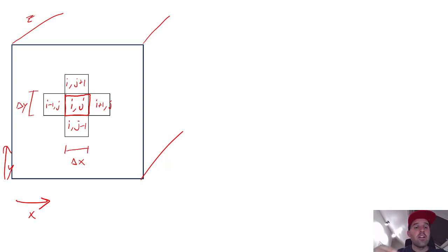All right, so let's think about an energy balance on this node. Because this node is completely embedded in our solid, the mode of energy transfer or heat transfer has to be conduction. It's not on an edge where it could be exposed to radiation or convection. It's just purely conduction. And what we're going to be doing here is, if you recall when we solved the heat equation, we shrunk delta x and delta y down to being really, really small. So here, with as much computational power as we can, we're going to try and have a high-resolution grid, which means that we can make this approximation assuming that delta x and delta y are really small.